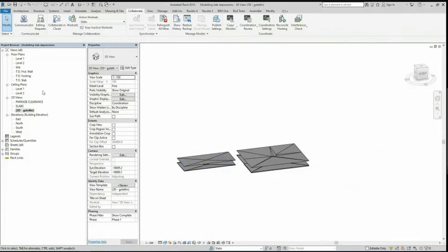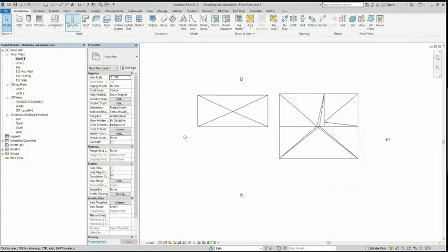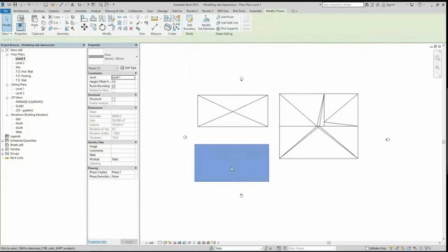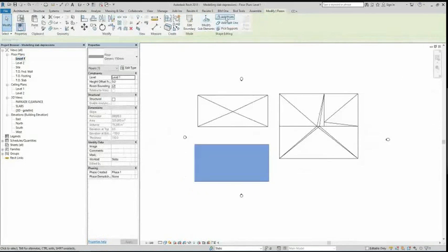And then I have an overall coordination 3D view just to see everything all in one 3D view. So I'm going to go ahead and get started just with a standard single thickness slab, just to show you that very quickly. So I'll just use 150 mil thickness floor slab, and we will create that. So once that slab is created, and I'll go 3D view to show you that, so you see it here.